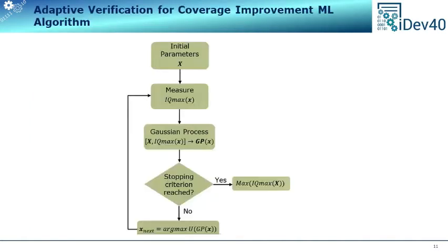The adaptive verification algorithm for coverage improvement starts with a predefined uniform distribution of input parameter combinations represented as a matrix X. Each column represents a VI, VQ, and T variables combination, meaning input voltage, forced output voltage, and temperature, and measurements are performed for every instance.